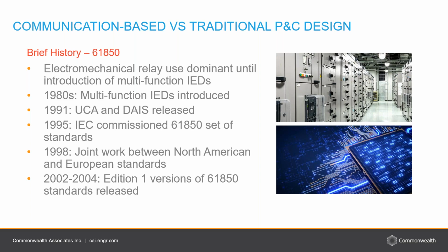The suite of standards in IEC 61850 not only defines the communication protocols for IEDs in the substation, but also describes the modeling and organization of data from the IEDs and its mapping to the communication protocols for the power system devices. The IEC 61850 standard was a response to the growing need for a higher and deeper level of automation in electrical grids. It had become clear that future demands could not be met with the technological limits of serial protocols like Modbus. Next slide, please.